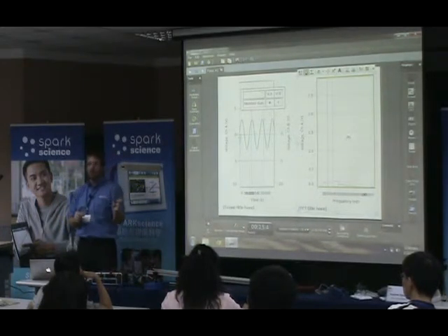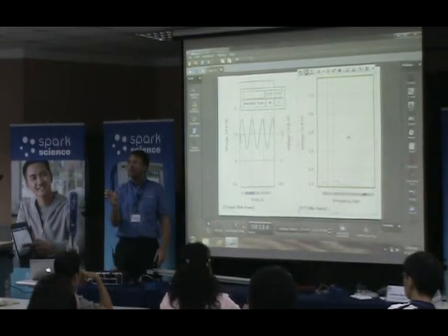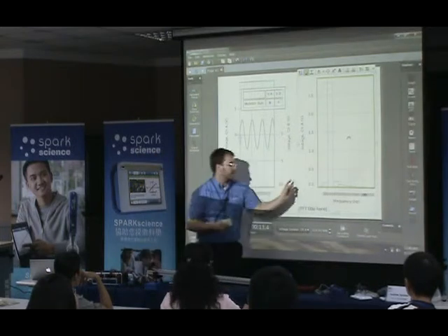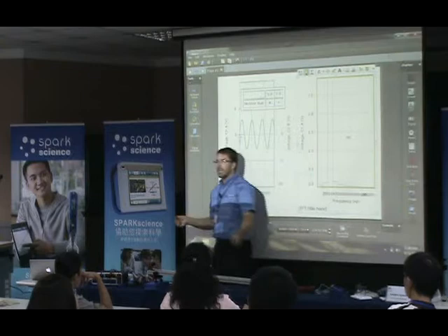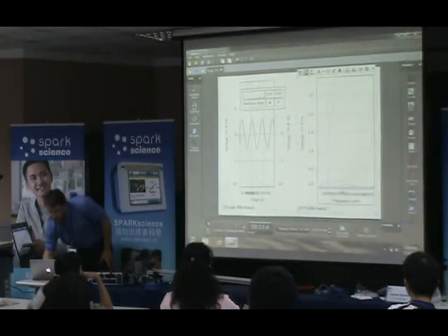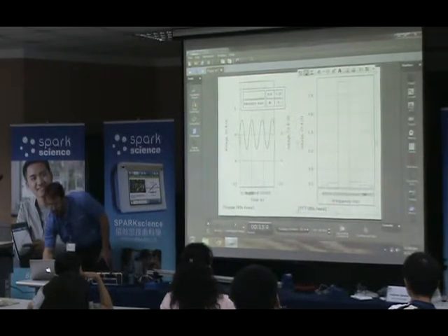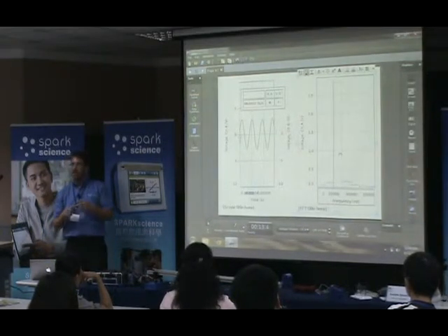is another big improvement over Data Studio. Data Studio had an FFT, but it was very limited by the number of bins that it could break down the signal to, and it looked kind of like this. It would be really chunky, and it would be over a very big range, and you couldn't quite figure out what the frequency is, right? So even if I start zooming in on this, even if I identify that it's somewhere around 30,000 hertz, it's still kind of blocky, right? It's still not doing a very good job of showing me what that frequency is.